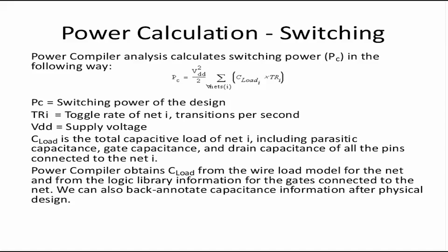This data comes from a separate file, which is called SPEF. The most popular format is SPEF. This process of reading the capacitance from a separate file is called back annotation. Right? We will see a lot of back annotation in unit files. If you don't understand it now, that's fine. We will see more details in unit files. It will be clear. What I mean to say is that accurate capacitance information can be fed back into the Power Compiler for accurate power analysis.